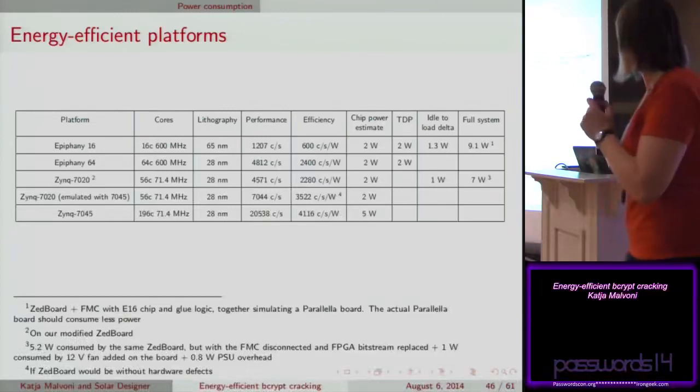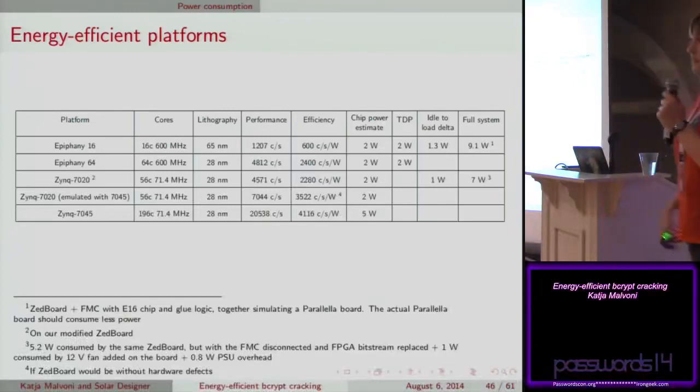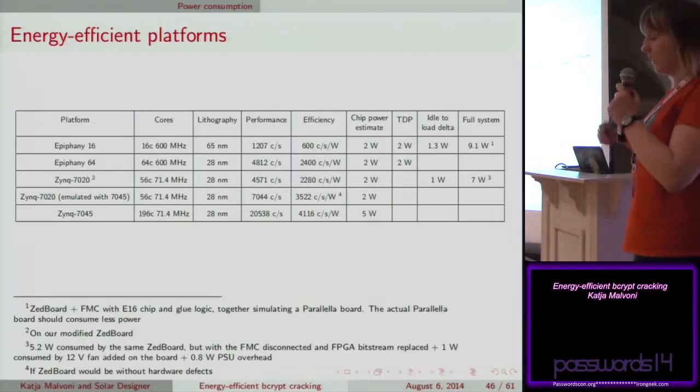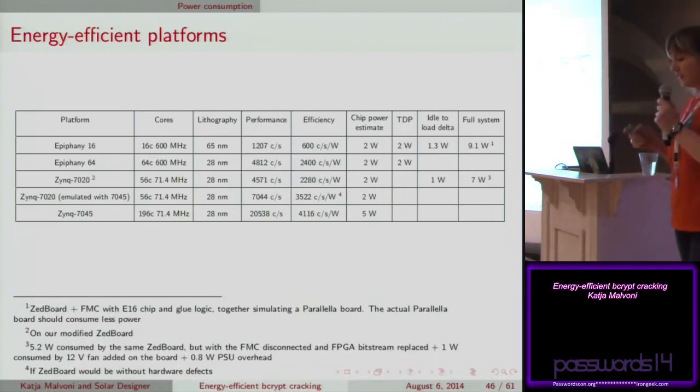Okay, I think it's actually the memory, because as you can see earlier, we changed the design to store initial values and then copy them, and that caused instability. So it certainly draws more power than before, or causes other problems. But yes, I think it's limited by BRAM.